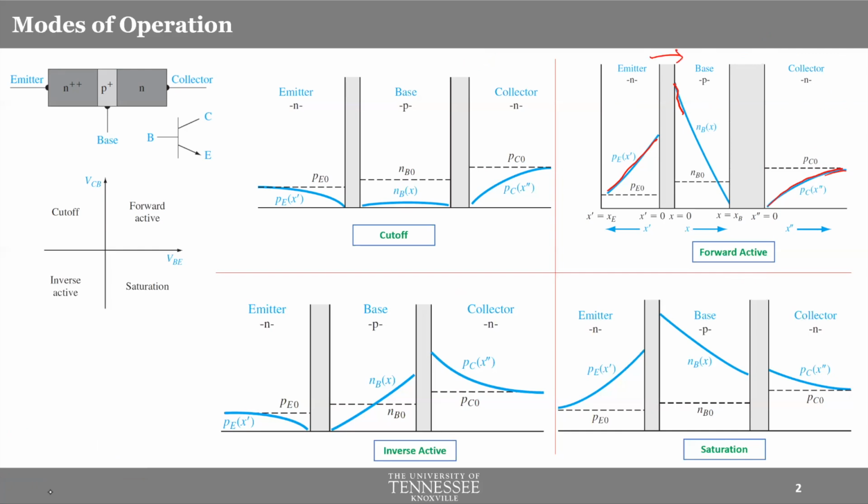Now, like I said, you have applied forward bias here. Remember one thumb rule, and that's logical, obviously. When you apply forward bias to a junction, the concentration of minority carriers will go up, will increase beyond the thermal equilibrium level. So it's similar to creating more minority carrier at the junction. And when you apply reverse bias, the concentration of minority carrier will reduce below the thermal equilibrium concentration. That means whatever you had at zero bias, you'll have more than that when you apply forward bias, and you will have less than that when you apply reverse bias.